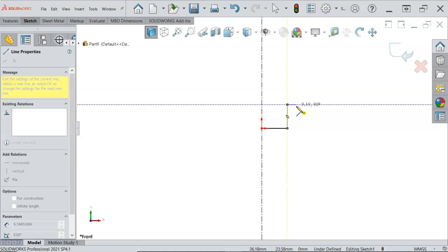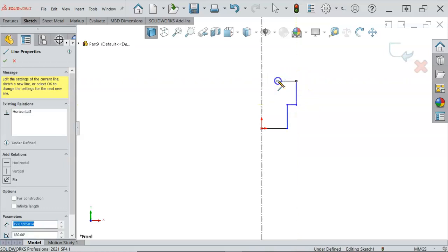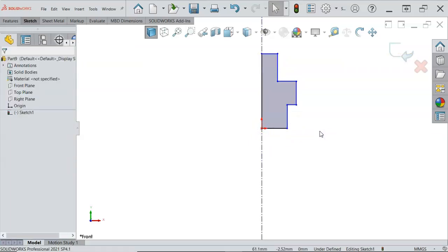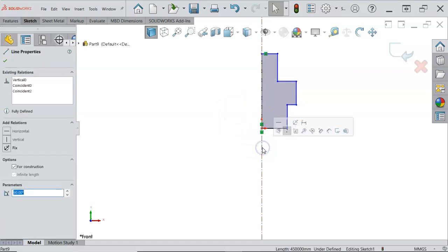And I've been doing the click drag, so just by contrast, the click click. And the click click has the advantage and the disadvantage that it's going to continue on into that next line. It's not really asking you where to pick. And then since I know when I revolve this, it's going to ask me to close it, I want to see that region. Then I'll go ahead and place it. The thing I have to remember for having that line is that when I place my diameters, I want to be on the center line, not the object line.